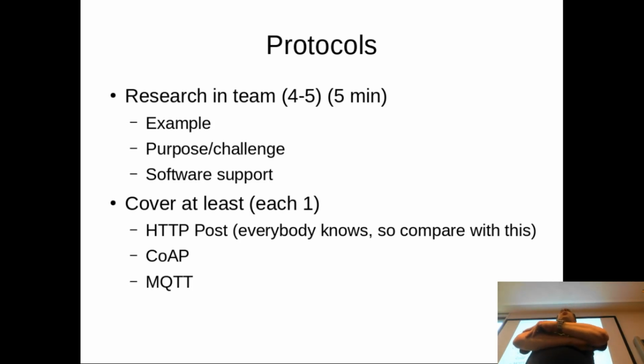How's the software support? Have you found some libraries? Does it seem difficult to use MQTT? No, there's tons of stuff out there for any type of device possible. Is it bound just to TCP, or can you, in theory, also use it on other? Yeah, usually it's on top of TCP/IP, but there are some implementations which work on UDP or just really on serial lines.